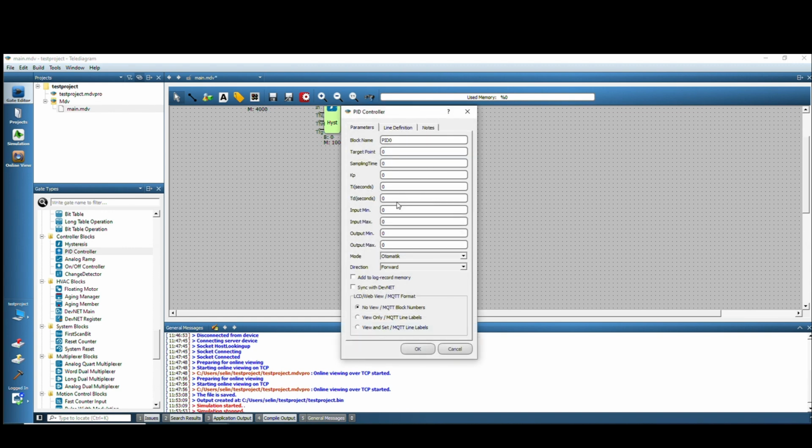You can define the minimum-maximum values for both the input and the output. For example, if the min-max range of the value connected to the Pro input is 0 to 1000, you can enter a value of 100 here. FBD control will be performed within the range you set, including the minimum and maximum for the output.